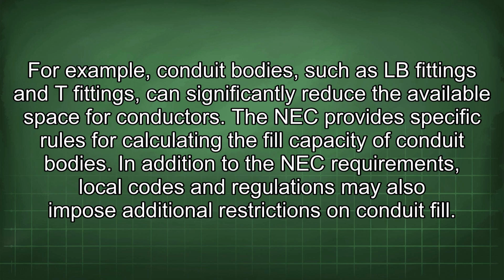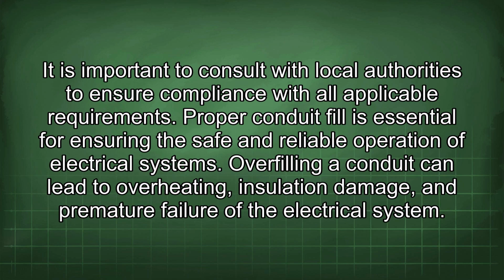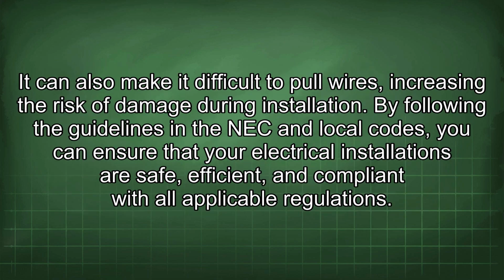In addition to the NEC requirements, local codes and regulations may also impose additional restrictions on conduit fill. It is important to consult with local authorities to ensure compliance with all applicable requirements. Proper conduit fill is essential for ensuring the safe and reliable operation of electrical systems. Overfilling a conduit can lead to overheating, insulation damage, and premature failure of the electrical system. It can also make it difficult to pull wires, increasing the risk of damage during installation.